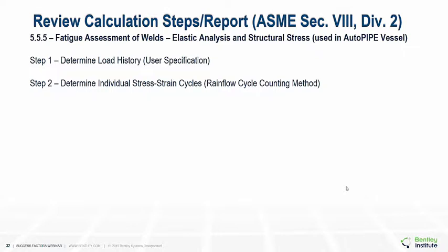The method starts with step 1. Step 1 is used to determine load history based on user specification. Step 2 is used to determine individual stress-strain cycles by the Rainflow method. These 2 steps have already been explained before.